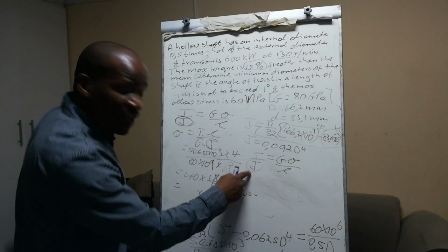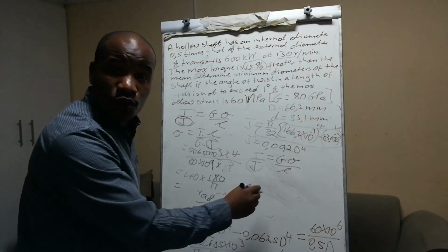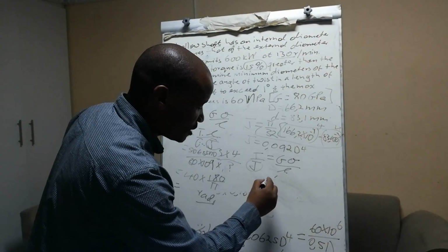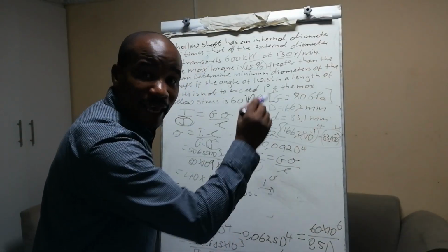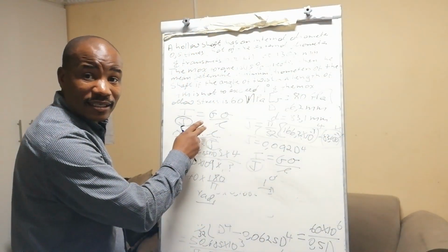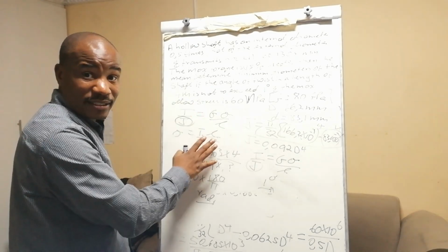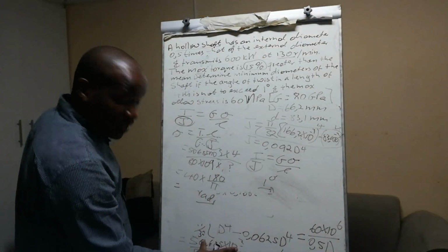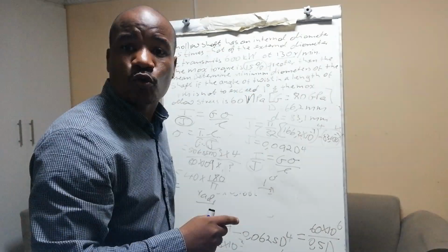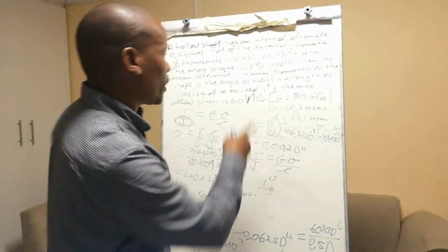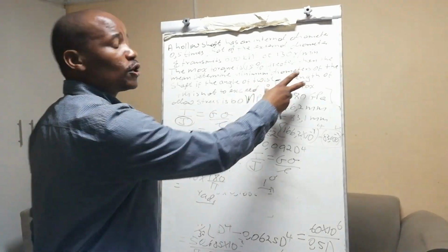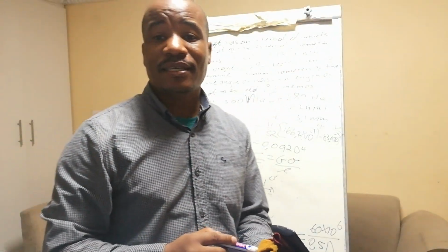You must prove that the values you get there will never exceed 1 degree. Then that's why that lecturer was right. You only ended up here, and those answers are wrong, when you prove them, that angle of theta exceeds 1, and you are told that it should not exceed 1. So you have to calculate another set of diameters.